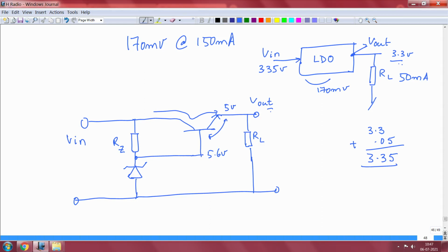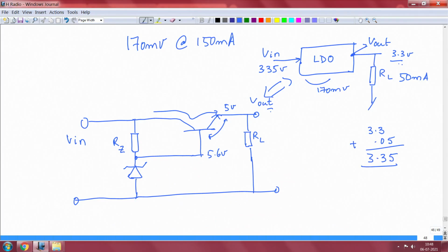Folks, the beauty is this LDO is essentially something that has a series pass element inside it, but for the difference that you are not getting a drop which is as huge as what you have here, but you have a very small drop between the input and the output. That is the only difference. Why did this paradigm come? Because first of all, technology has changed, right.